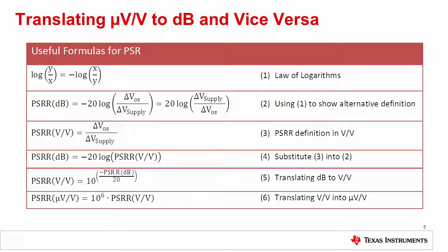This slide summarizes the various PSRR definitions as well as general mathematical relationships. It is common to see PSRR represented in volts per volt, microvolts per volt, and in decibels. These equations allow you to make these translations.